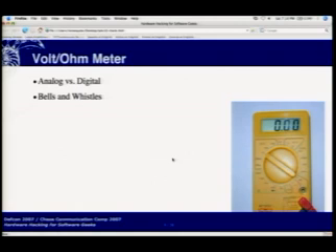Otherwise, these are fantastic. The basic ones, you'll just get ohms, volts, you measure resistance and voltage, current, usually a diode or continuity check. You can get all sorts of crazy features. Capacitance meters are pretty common. Some of them have temperature sensors via thermocouples, which are useful for controlling your toaster oven. No contact voltage. Oh yes, clamp meters for going around something that you believe to be carrying a current, that can pick up the current by induction.